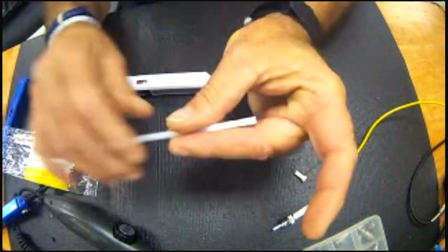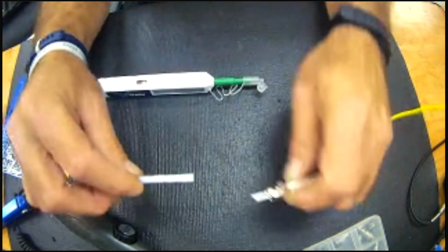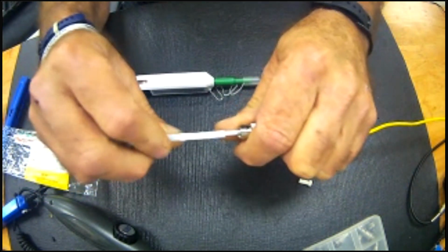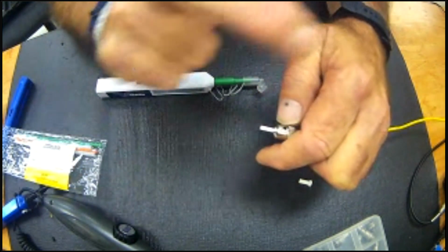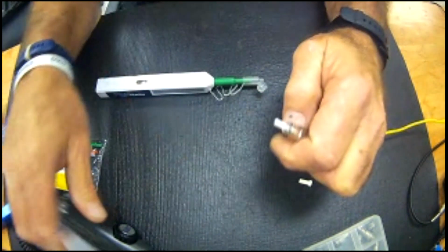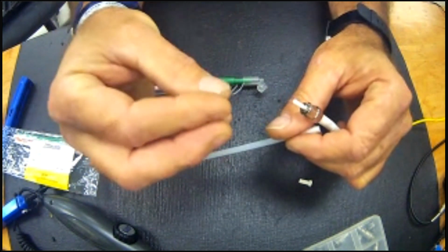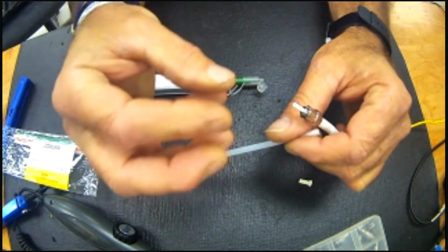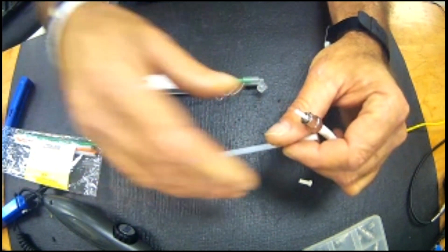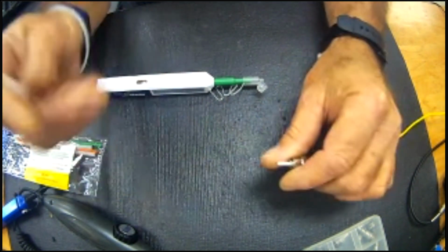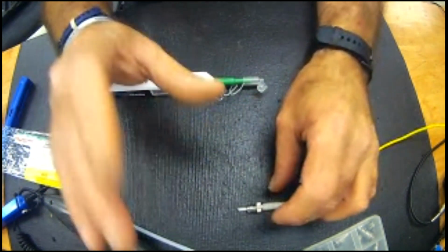Think about this as a reverse Q-tip design. We have a full synthetic material inside of a poly tube that gives me the ability to press against the surface of the zirconium and rotate, always rotating one direction. You basically want to move the dirt from the center core away to the outer perimeter. Because this material is compressed inside of this poly tube, when you press it, it folds apart, and then as you release it or pull it away, it actually will lift the garbage off the end. The poly tube also allows you to reach inside of connectors, which is advantageous.